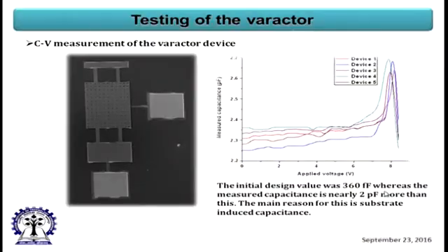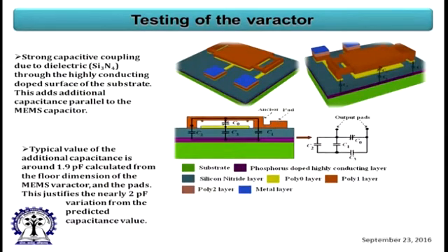Finally, what I wanted to see is the capacitance change, so I did the capacitance measurement, CV measurement. You see how the capacitance is changing. Finally, when it goes to pull-off, it shorted, and since the machine has a compliance, it immediately stopped, so the current goes down. This is the variation of the capacitance versus frequency of 6 devices.